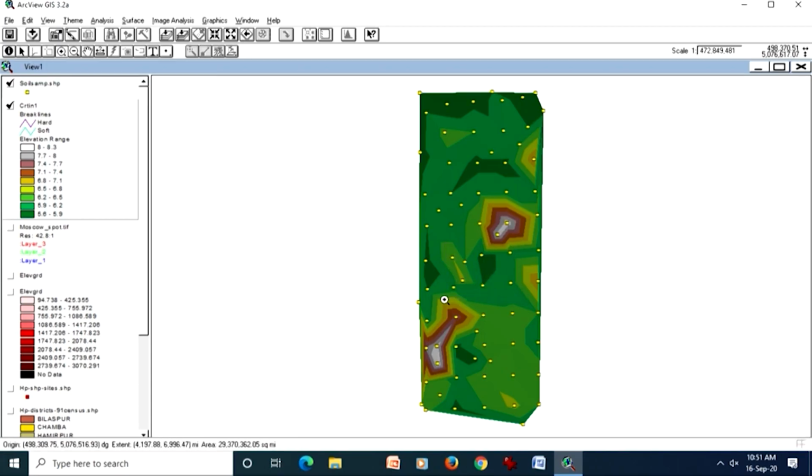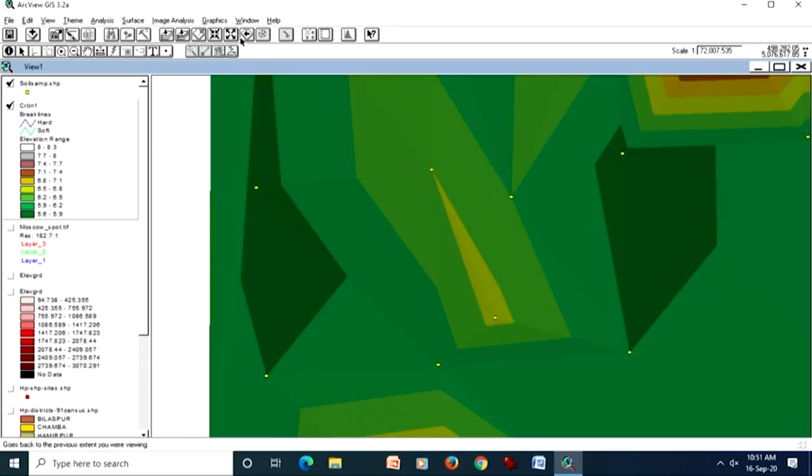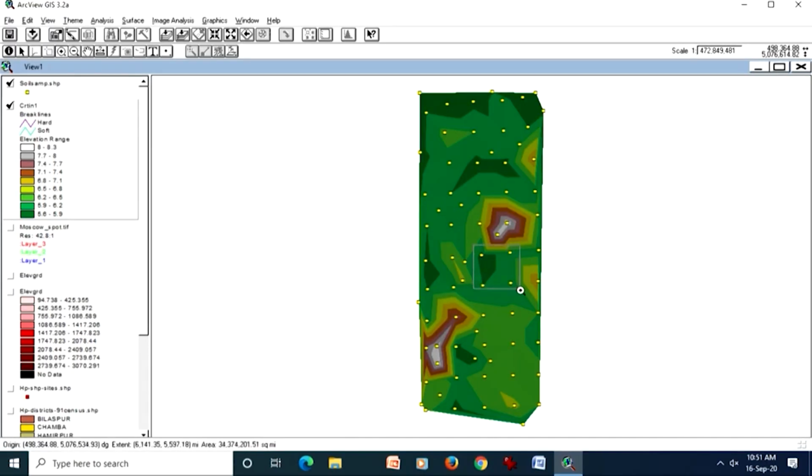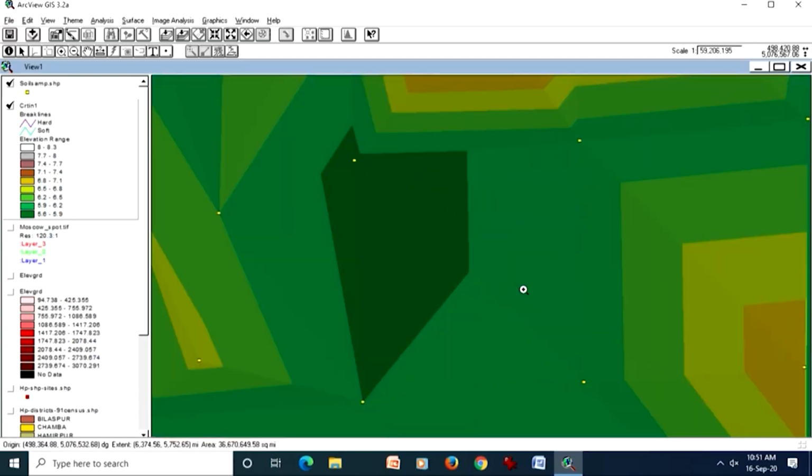So if I zoom here, I am getting small triangles, but if I zoom in on this part, I am getting larger triangles which have been formed. As discussed earlier while discussing the TIN in the theoretical part, TIN is adaptable to relief roughness or changes, whereas raster cell size is fixed and within one cell everything is an areal average. But in the case of TIN, it is not like that. So, TIN is basically a completely different kind of data model to represent a surface.